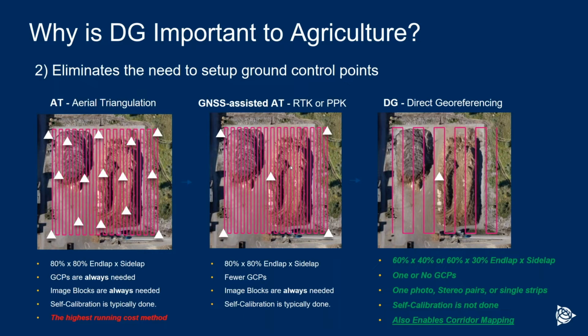And then we said, well, hey, why not just add an IMU or inertial system as well? So what does that get us? Well, as I explained before, because we can use mathematics to position the information on the ground, we don't need any ground control points. We'll need one or two checkpoints to make sure that the data being captured is accurate, but we don't need all of these ground control points that you need in the other methods that I've shown here.